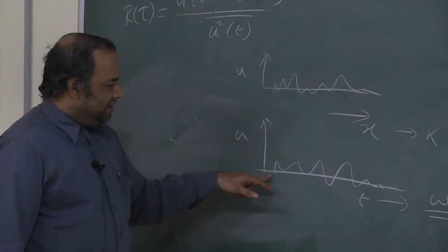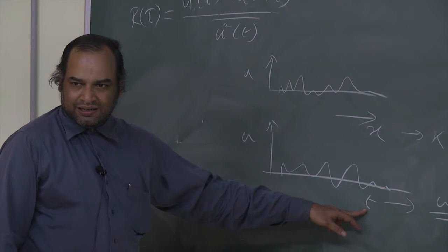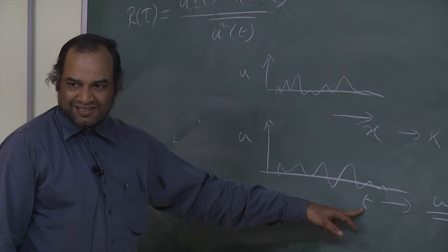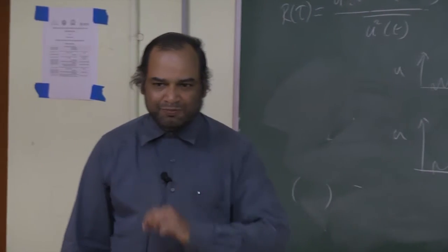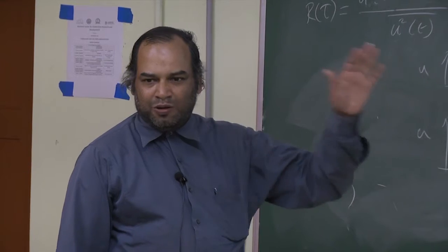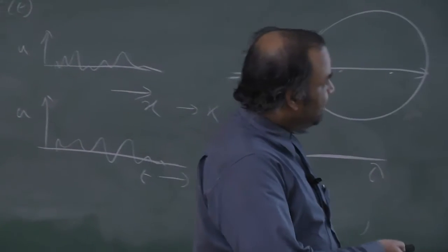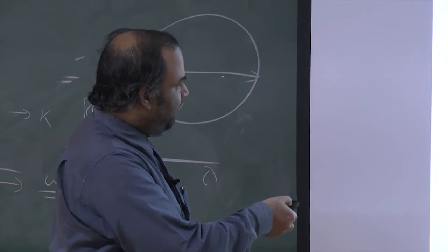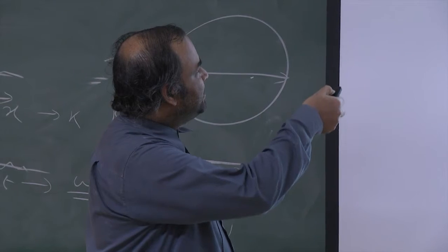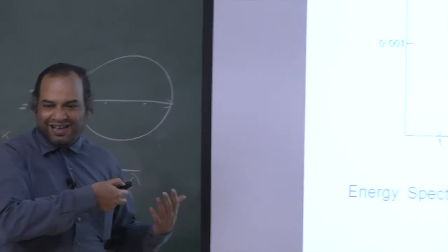Whereas here, if you want this, traditionally what is done is it uses hotwire anemometry, for instance. It gives me the time history at a given point, a point measurement, as PIV is a global measurement. So what this shows, first of all, is that more energy is contained at the largest scales.